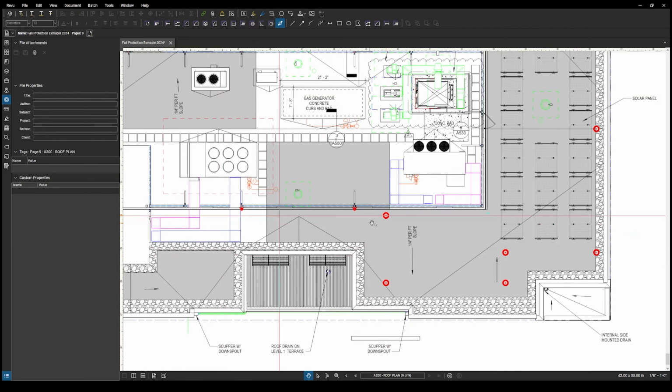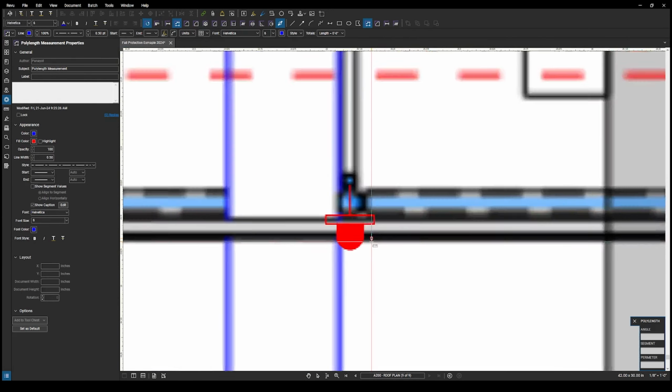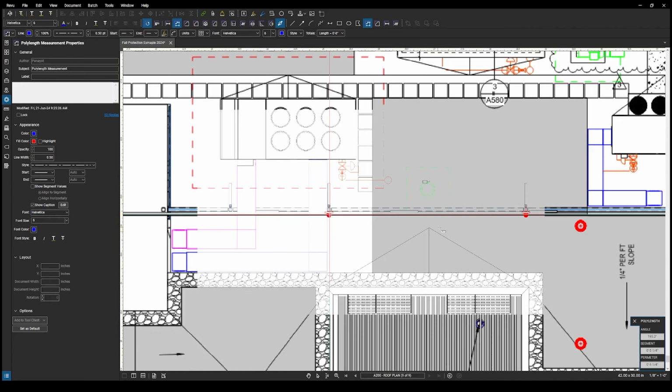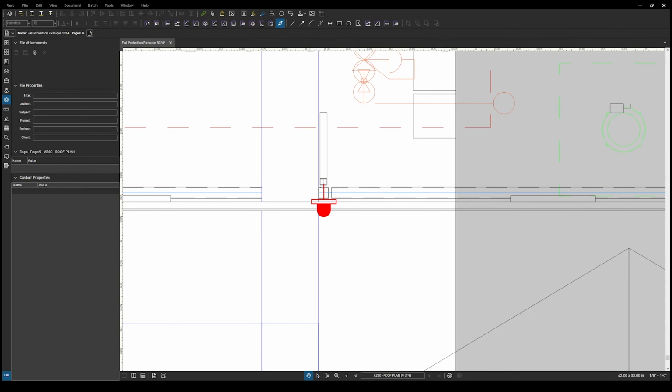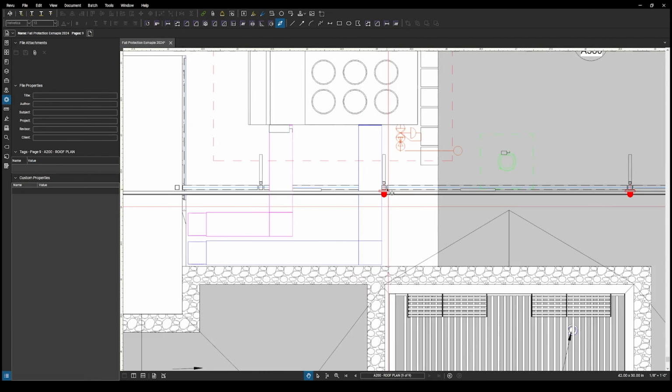So with that said, our anchors are already all set, so we can start measuring the cable, which is going to start with our polyline measurement tool. That's this over here. It's what I like to use because it automatically gives me measurements instead of having to put a line here, measure them, add them all together, things like that. So what I would do is just go around and hit every anchor point that's at a corner. Just going to snap it on.